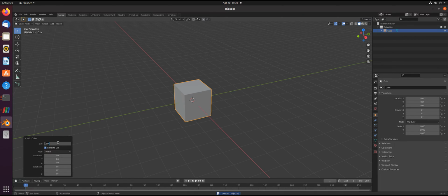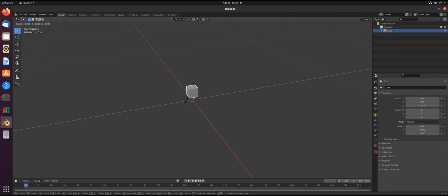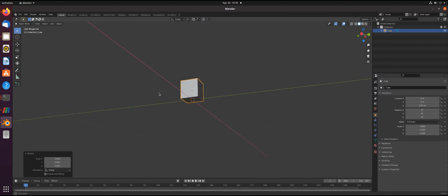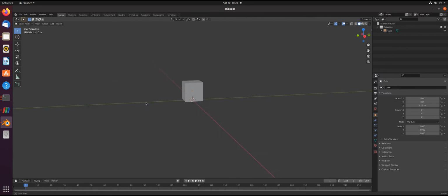After Blender is loaded, I select every object by pressing A on the keyboard and then delete. With Shift-A, I add a mesh object in the shape of a cube. The size of the cube can be adjusted to the size of the object I want to create. I want it with an edge length of 100 mm. I select 50 mm here, for example, to demonstrate how you can scale up the object using the key S and then type in 2 to scale it by factor 2. To model a shape you want, you have different options. One is to select the face and drag it.